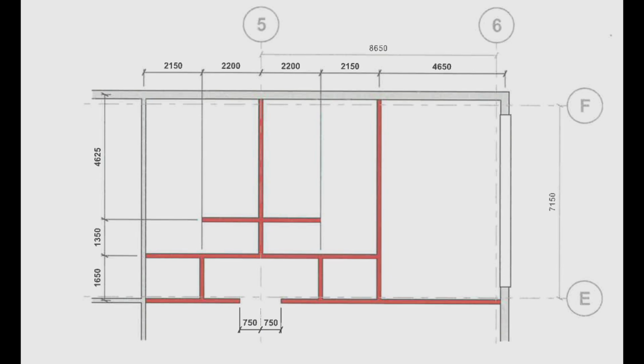Once the concept model is established with these Grade 1 generic components, we can later replace them with more detailed, composite, and manufacturer-specific system families, adding complexity only when the design decisions require it. Working this way creates a smooth path from early design through coordination and eventually toward fabrication-level detailing. During this module, we also introduce system family libraries and discuss how they should be managed and applied. You'll also learn the limitations that come with structural beams and columns when working in Revit MEP.